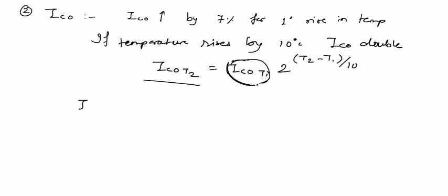We know that the equation IC is equal to beta into IB plus 1 plus beta into ICO or ICBO. This ICO increase will increase the collector current IC, and if collector current IC increases, again the load line, the operating point will be shifted.